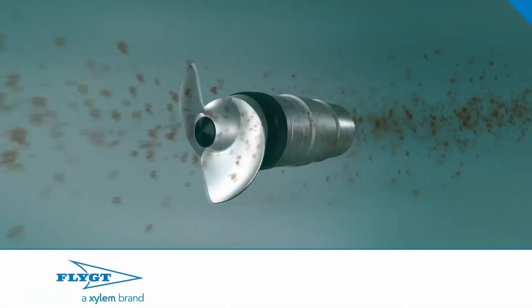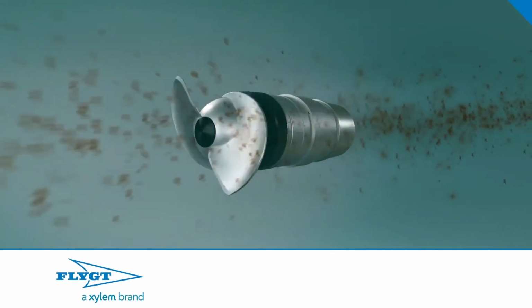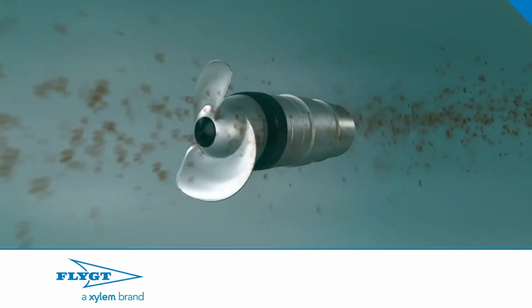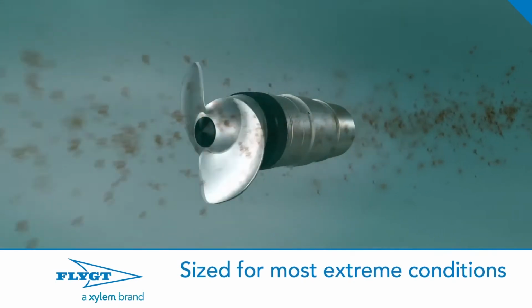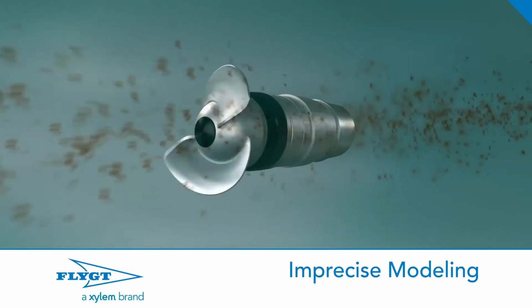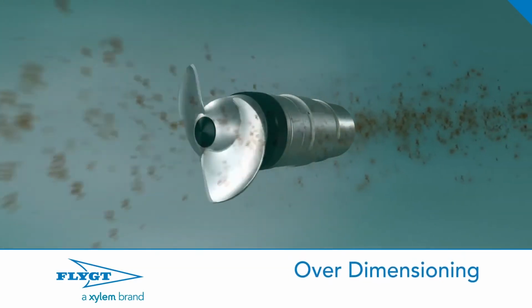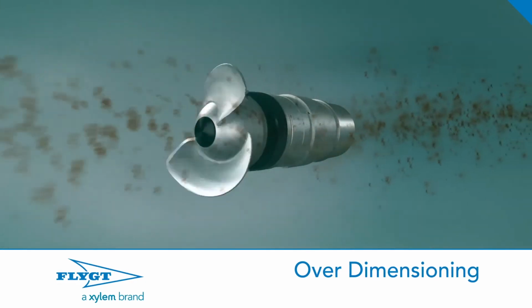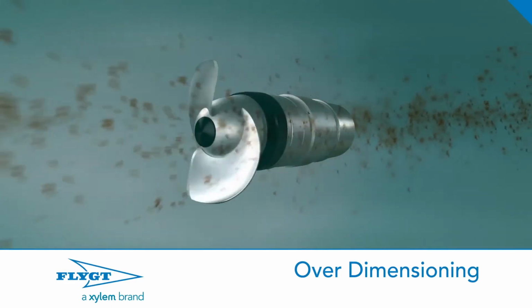Choosing the appropriate mixer is important. Today, however, most mixers are oversized for the job they are doing. This is usually because they are sized for the worst-case scenarios. The manufacturers use older or imprecise sizing models due to the lack of experience in the application, or the mixers were sized without adequate consideration for issues like pre-screening, sedimentation, and location of inlets and outlets in the tank.